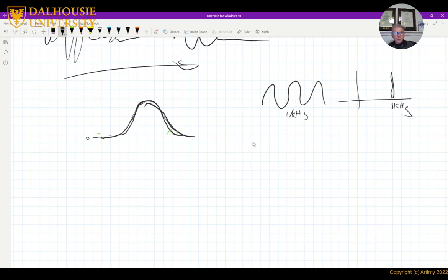But when I have multiple frequencies, then I may have multiple lines here in the frequency domain, and the bandwidth will be measured like f high minus f low, right? But what if the bandwidth actually goes down almost from infinity to minus infinity? So it's never zero, right? It's never f high minus f low. It dies down slowly, as you see here.